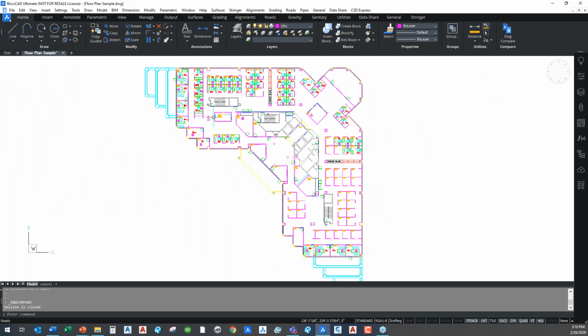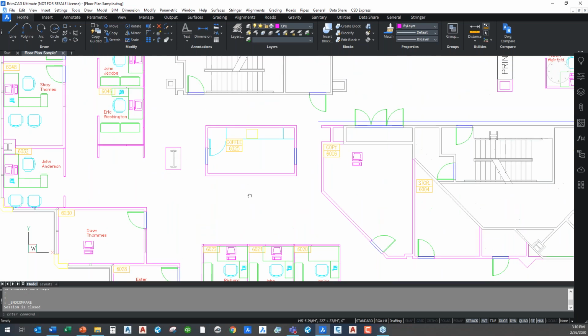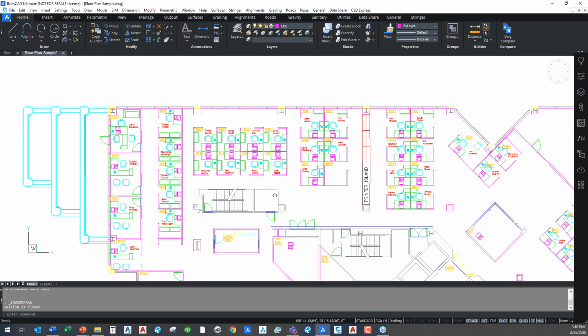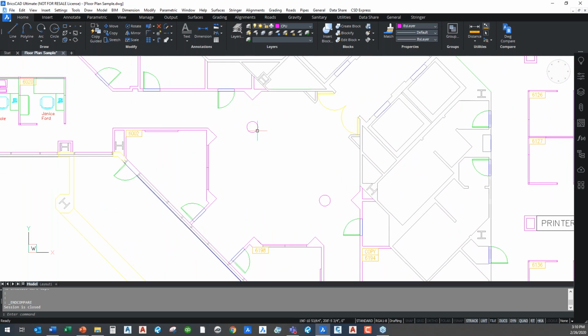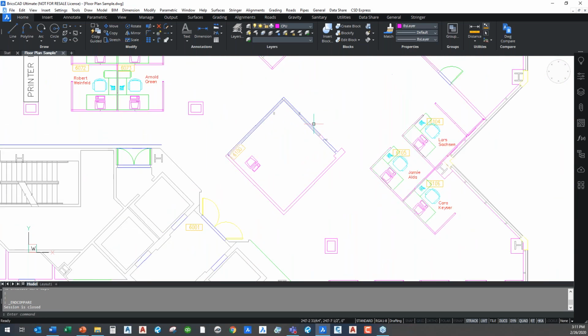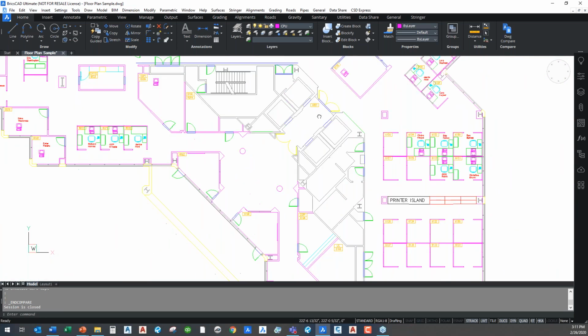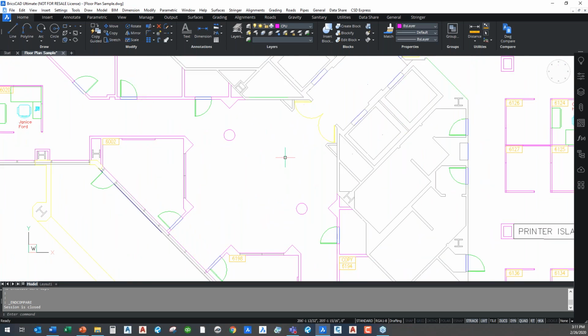Just like that, I was able to make all the changes. And you'll see all of the offices that got deleted, those are gone here and here. You can see the 2 new columns that were put in revision 2. They're here. The rotated room is here. And what's nice is that when it brought over those items from the revision 2 file and I told it to keep them, you'll notice that it was also cognizant of layer, line type, scale, and location.